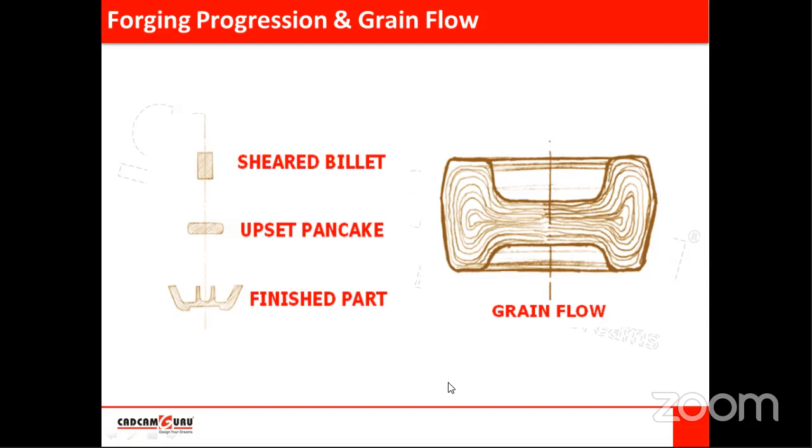For the connecting rod also we have seen the initial shape. The initial shape doesn't look like a connecting rod. They place it at one end, and then it is transferred to the connecting rod dies. Then after two or three stages we will get the final component, and then it is printed.